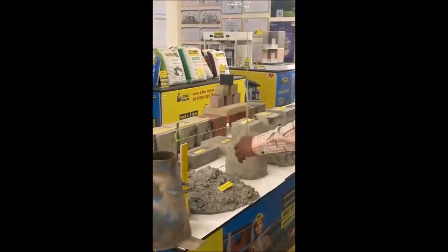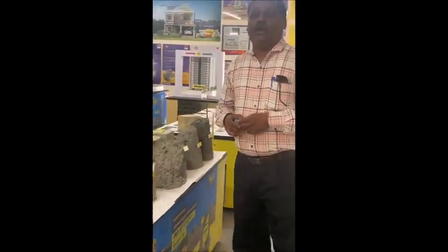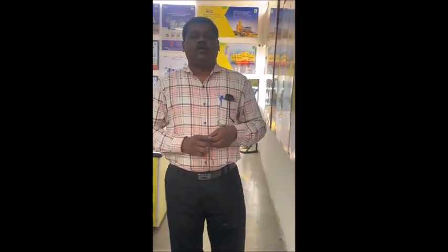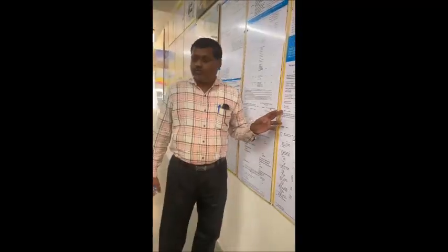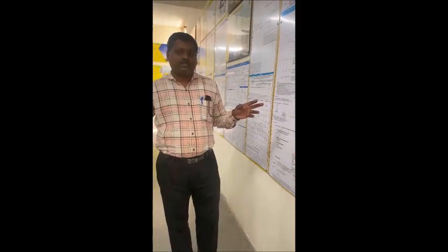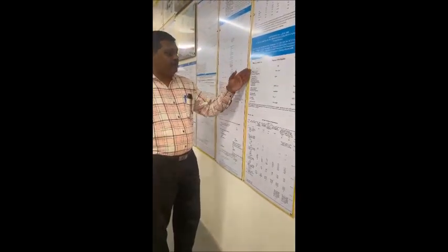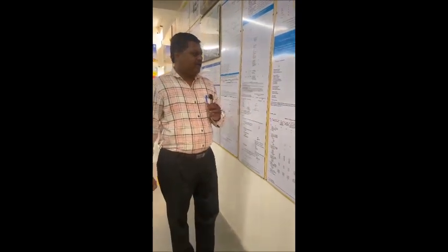If you measure this value, it is about 185 to 190. Now 185 to 190 is the slump value, and that too of a dispersed cohesive mix. Then my question for all of you students is where it is suited. You can open IS 456 and go to that table. This table is on page number 2. Go to that page, and according to this 180 or 190 slump value, tell me where this collapse concrete, which is having 180 to 190 slump, is suited according to our IS 456 table. For which placing condition this type of concrete is feasible, you should study and give the answer. Okay, so I am continuing.